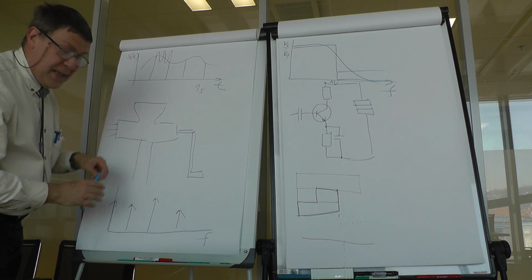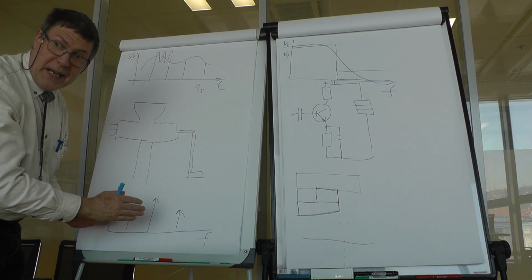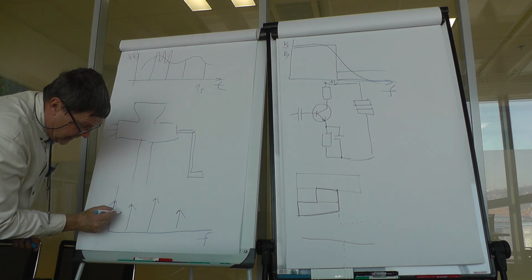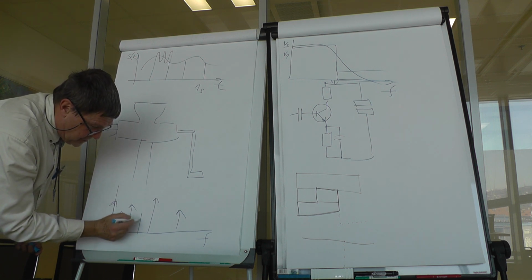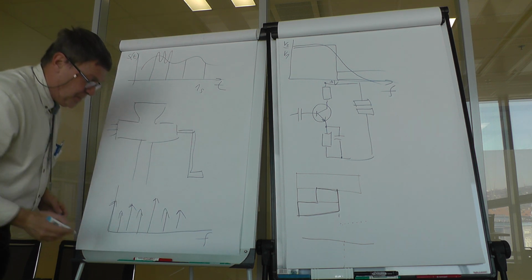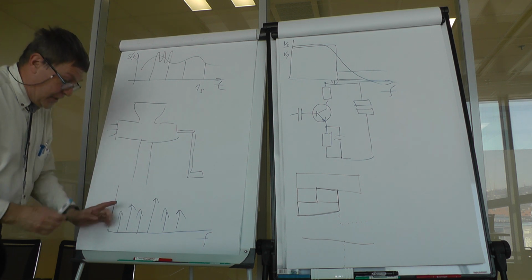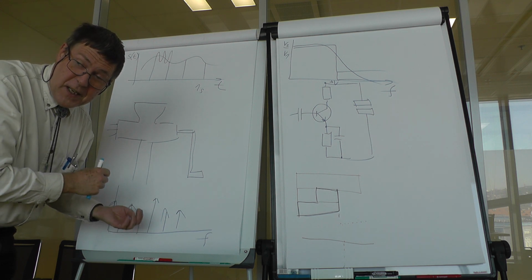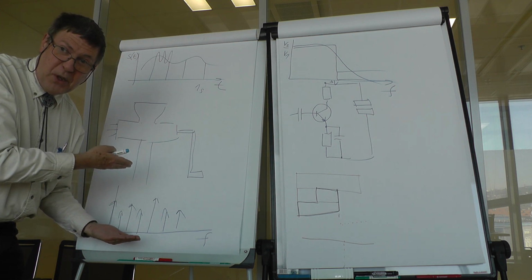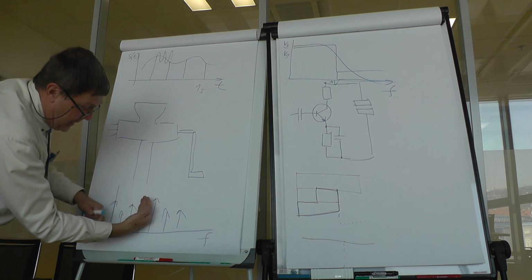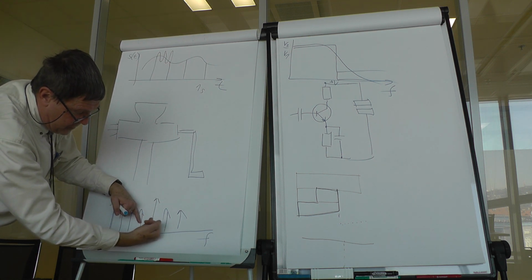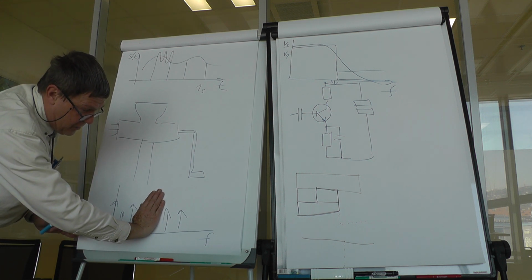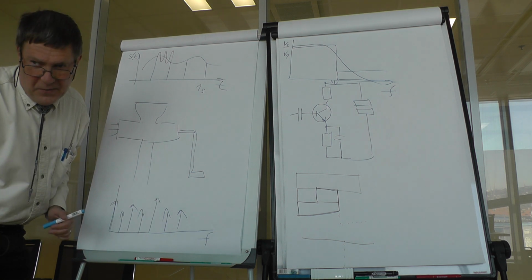If I oversample, so if I make 2 times more samples within the same slot, I will get a set of different components, and each of those frequency components would itself suffer from the maximum error of 100%. But if I average 2 together, so this combined error for the average would be only 50%.